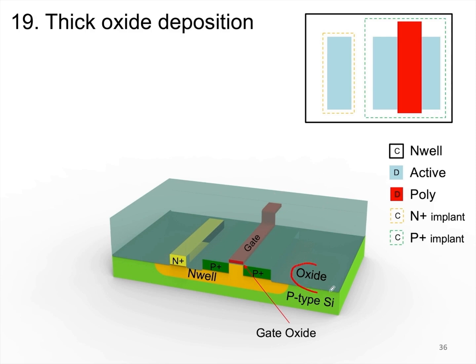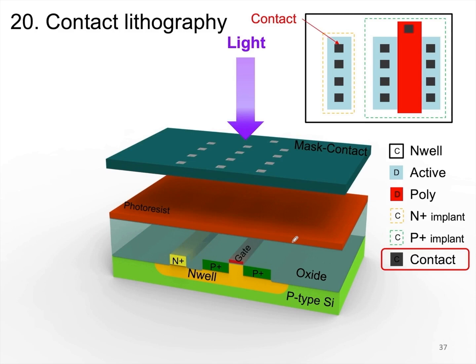We keep etching until we reach our source or drain region, substrate contact, and polysilicon. After that, we perform tungsten deposition, which is a metal deposition process. This allows us to form metal contacts in the areas where we just etched some holes. These contacts are small pillars made of metal that connect our substrate, source, drain, and gate together. Next, we need to connect them to our M1, right? So we will process M1.